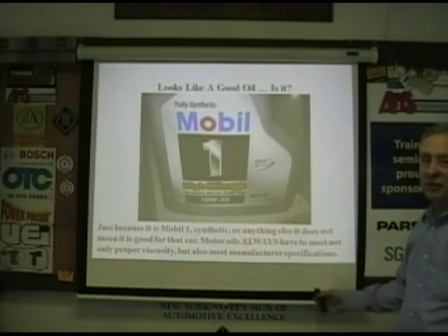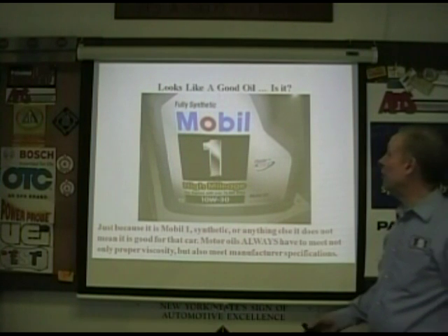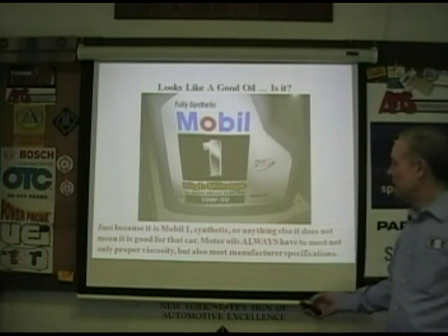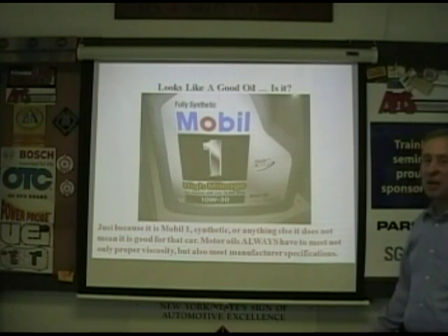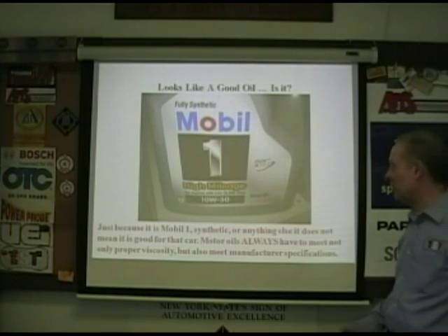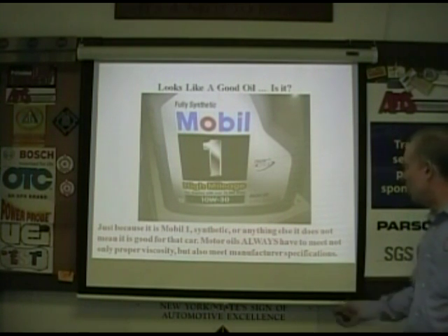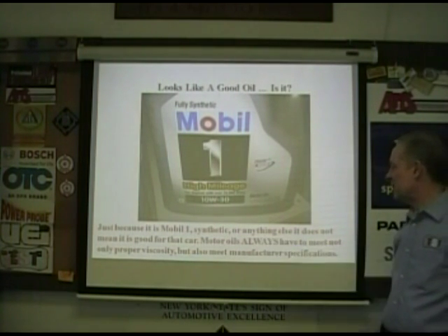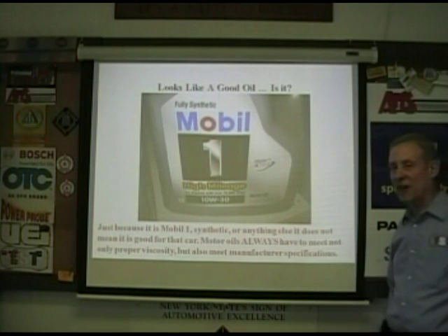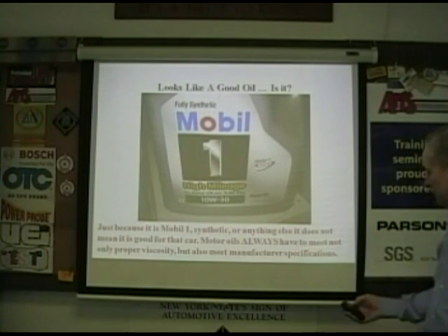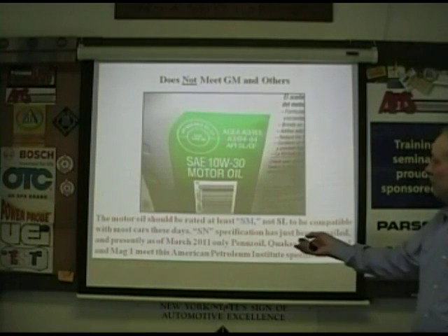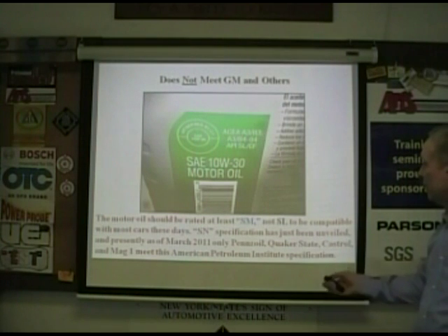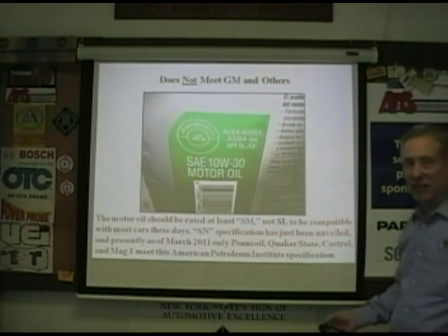Alright, this Mobil 1 can here looks like a good oil. Is it? Just because it's Mobil 1, synthetic or anything else, does not mean it's good for the vehicle that you're currently working on. Motor oils always have to meet proper viscosity, but they have to as well meet manufacturer specifications. What's missing from this picture? Motor oil should be rated at least SM nowadays, not SL anymore. SN is out as well.